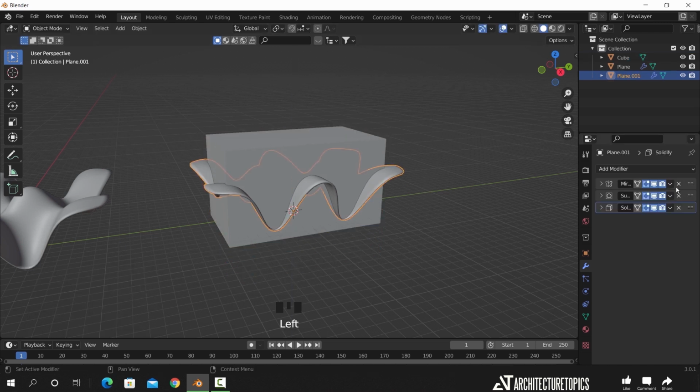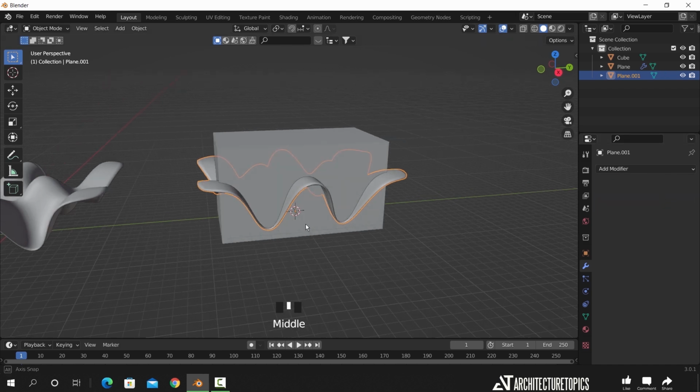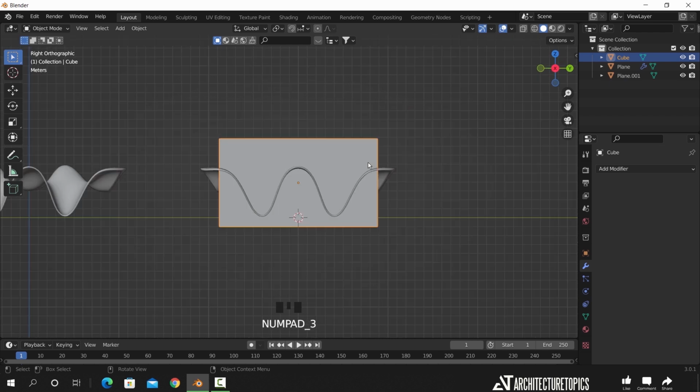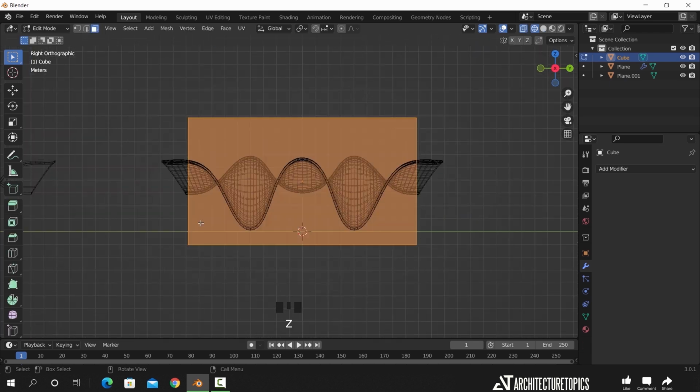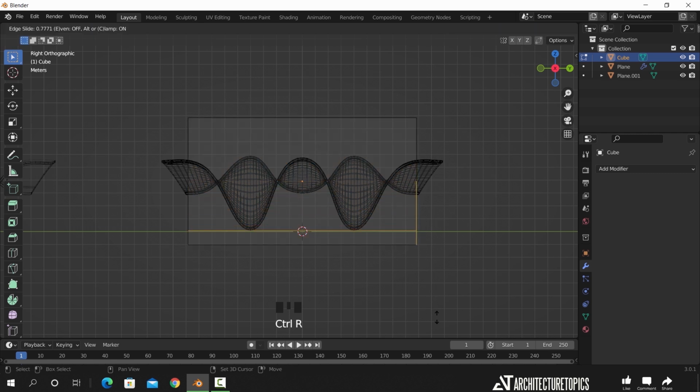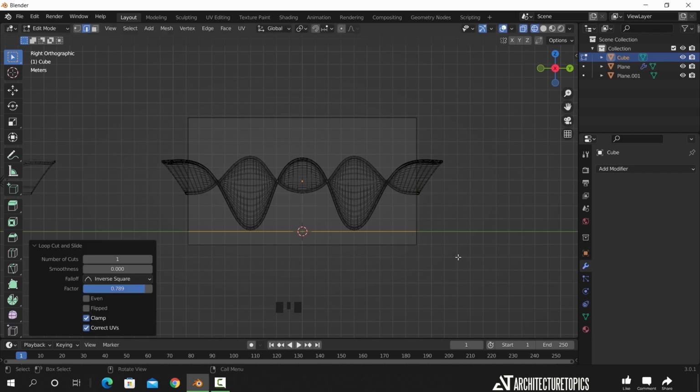We will use Boolean to cut it with the shape copy, but before that, let us apply the modifiers on the shape copy alone. We also need to add a couple of cuts on the cube. Boolean usually ruins quad faces, and in most cases you can't add cuts to a Boolean mesh in a normal way, so I will mark the floor level, the mid and center frame lines with 3 cuts, then we can go with the Boolean.